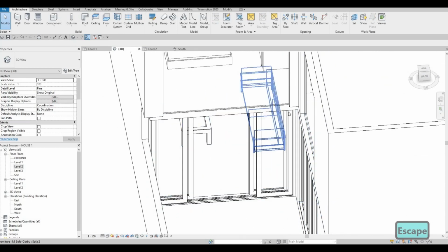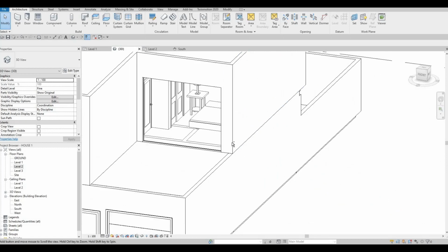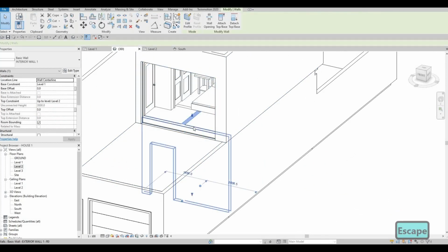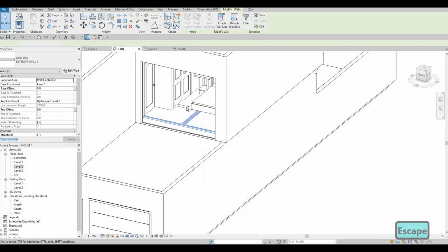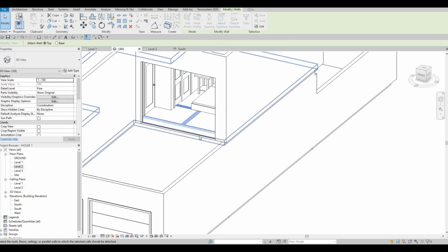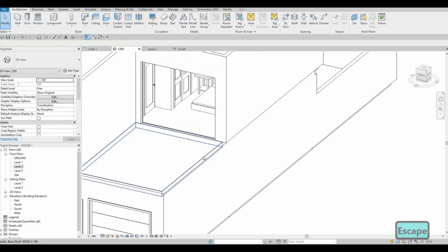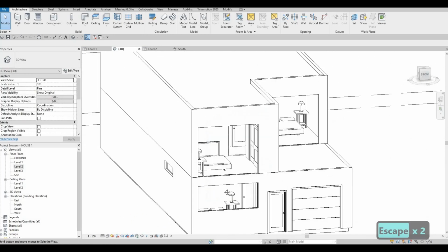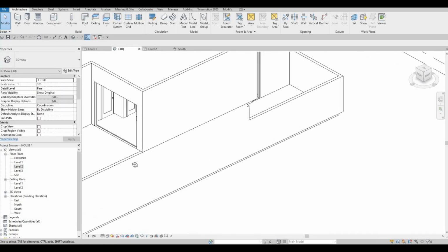Okay. This one as well. Some of the flooring right here. You can select them multiple times by holding control. Select top base offset and then select the floor. So that's how you make those go lower.